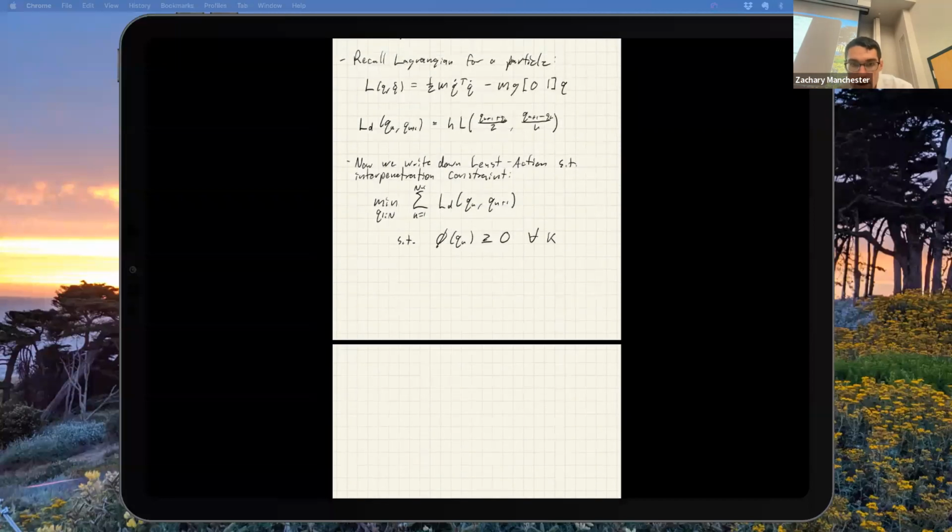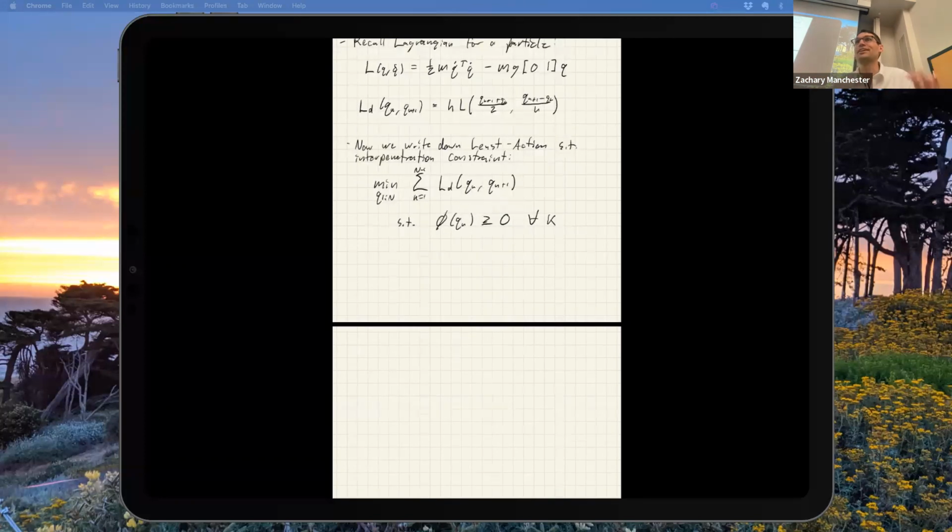So now I'm just going to write this down. It's literally exactly the stuff we did last time, where you take the big derivative, play with time steps, and so on. All that's the same as when we did just joint constraints. The only difference is you get the exact same joint constraint stuff, the discrete Euler-Lagrange equation, plus these extra complementarity conditions associated with inequalities. So I'm not going to do the whole thing again. I'm just going to write it down from last time and then tack on the extra stuff, if we all agree that that was somewhat painful and not that fun. So